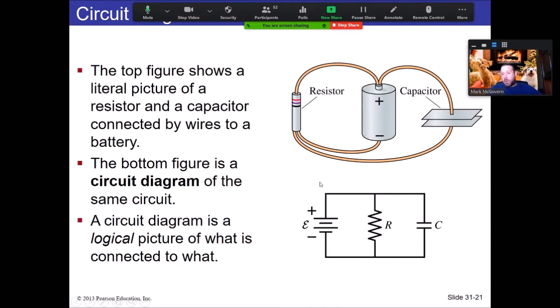Could it go into the junction here, and then the right side goes into the junction, and then things go out the bottom? Maybe. Here's the beautiful thing about this. You can guess wrong as long as it's logical. For example, you can't say that all three currents at the junction go in. That's clearly wrong, right? But it's possible that the horizontal ones go in and the bottom one goes out. That's logical. That's possible. And you can guess that in your circuits.